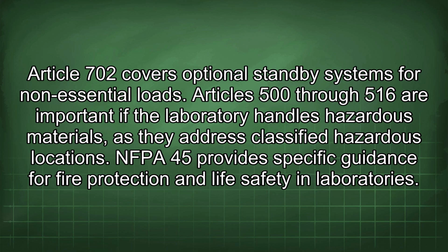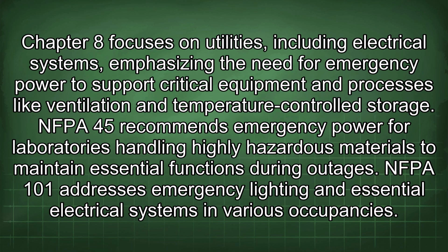NFPA 45 provides specific guidance for fire protection and life safety in laboratories. Chapter 8 focuses on utilities, including electrical systems, emphasizing the need for emergency power to support critical equipment and processes like ventilation and temperature-controlled storage. NFPA 45 recommends emergency power for laboratories handling highly hazardous materials to maintain essential functions during outages.